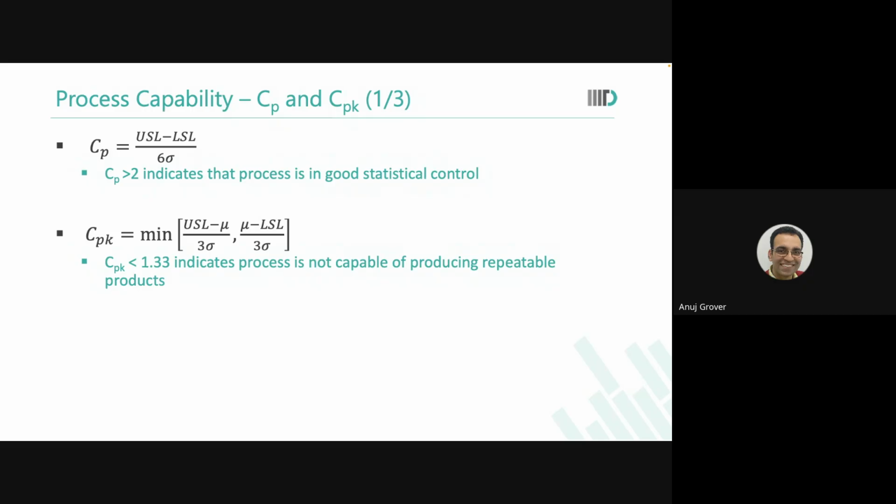But because of possibly temperature fluctuations at the time of manufacturing or something, it could happen that this is 15% of VT. Now, VT minus 3 sigma is VT minus 45% instead of VT minus 30%. Are you able to see this?